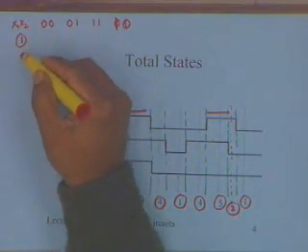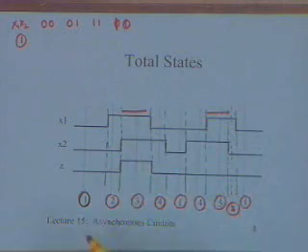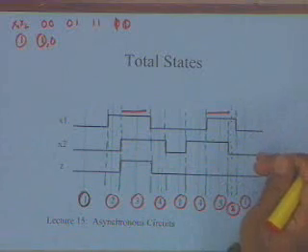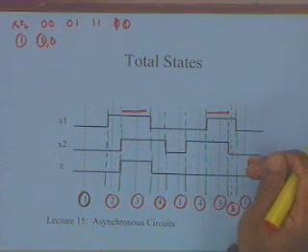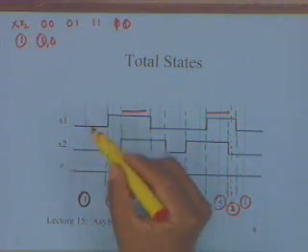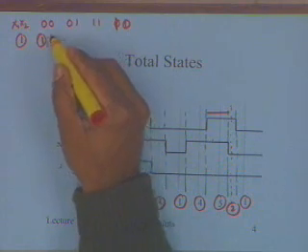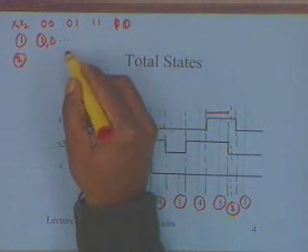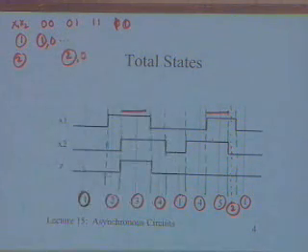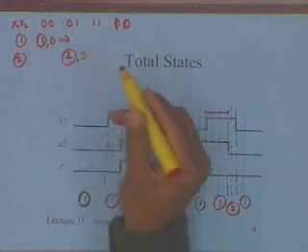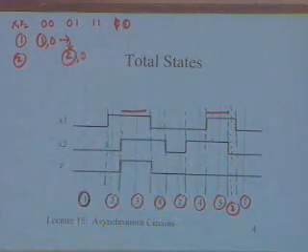So each row I will have for each stable state. I am in a state which is 1 with my output 0. Now my input is going to change. If my input is going to change to 1 0, I am basically moving from this column to this column. So I will go to the state corresponding to stable state 2. So this is the change. When I am moving from here to here, the inputs change, and due to the inputs the state changes.